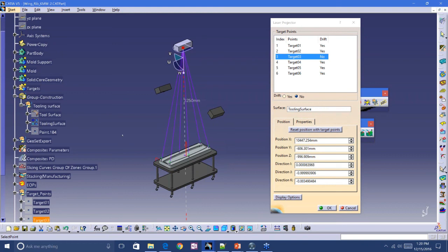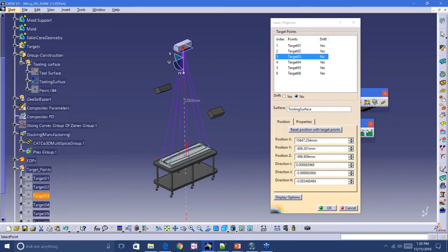And so the way this works is it's going to look at the composite stacking, the first ply group that it sees here, and in this case I only have one, it's going to pick up that information. So the fact that this arrow is pointing up in the correct direction for my ply layup is because the ply group has been defined like that. I can change it if I like. I can override that. But I want it to be pointing up.